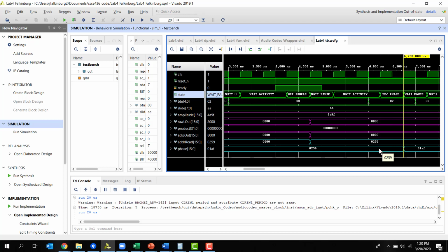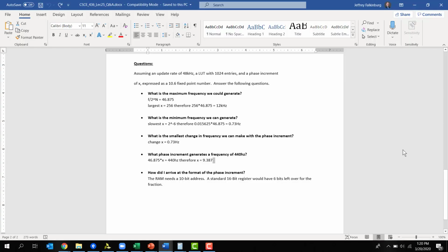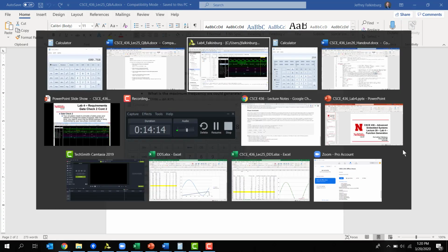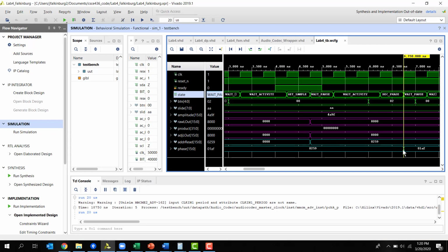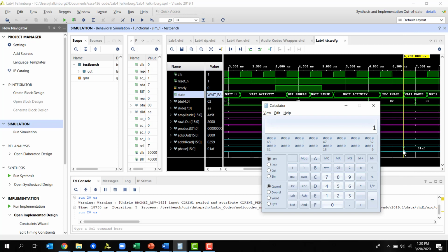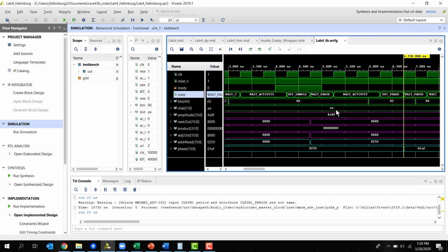So I have this button that's decrementing my phase, and you can see based upon the slider switches, it will decrement my phase. And if you do the subtraction on that, you can find out how much I decrement by. So 259 in hex minus 1AF, we get AA, which is what was on my slider switches. So a 2.6 value I'm subtracting right from the 10.6 value. And I get my new phase index.